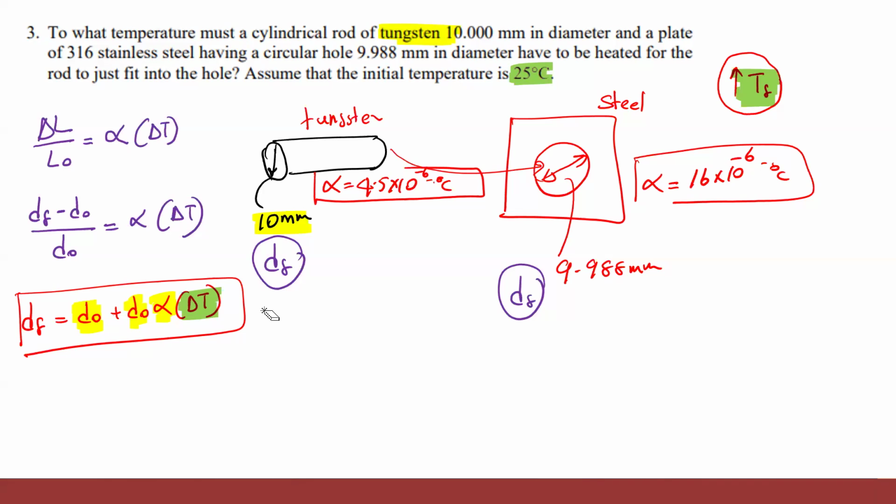You can't cool one material and not heat the other. When you cool this one, you make it smaller. When you heat up, it expands, except water. And the material expands, but the hole doesn't get smaller just because there's a hole in the middle, right? It makes the material around the hole expand, and the hole gets smaller.